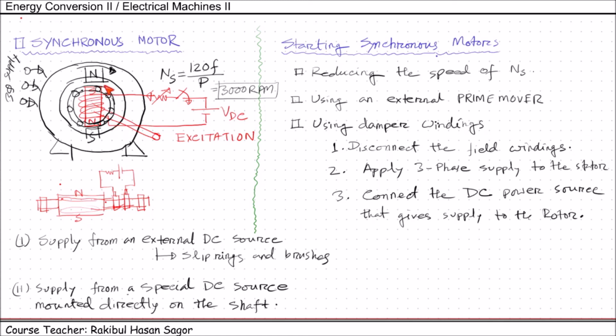From the operation of this synchronous motor, it is evident that even though we increase the load on the shaft, as long as they are interconnected, the rotor will not change its speed, rather it will keep moving with synchronous speed. Now, if we keep increasing the load, as long as they are interconnected, it will keep moving with synchronous speed. Its speed will not be decreased, unlike the induction motor case.